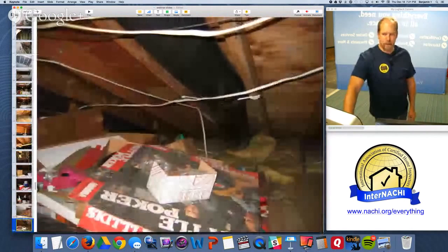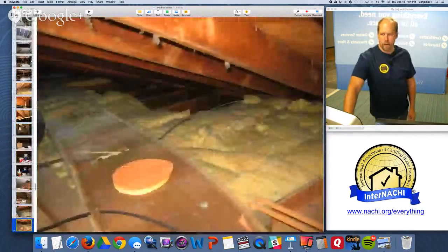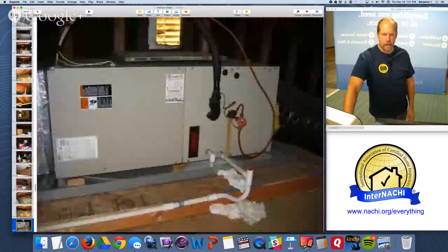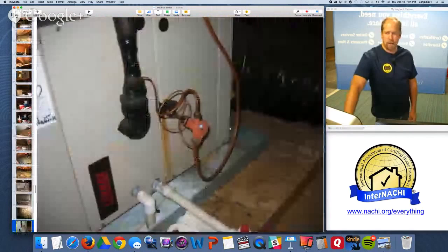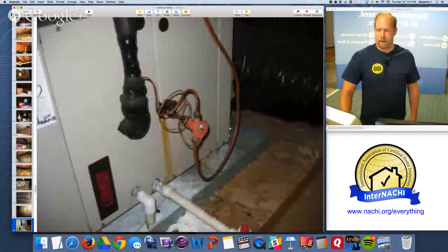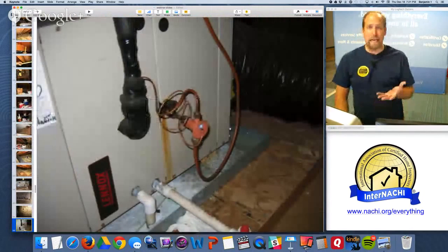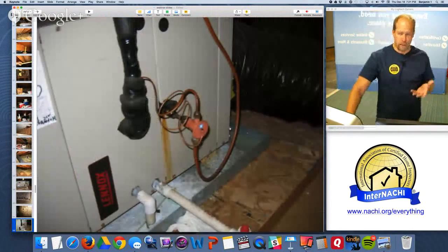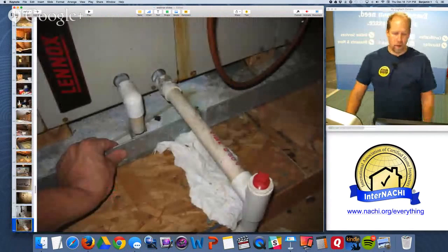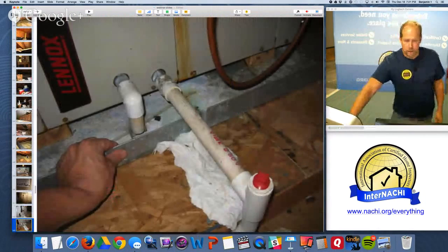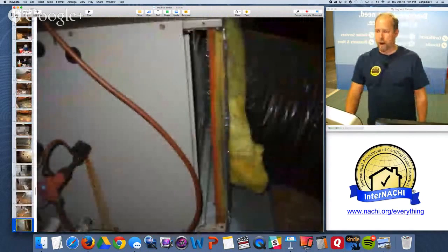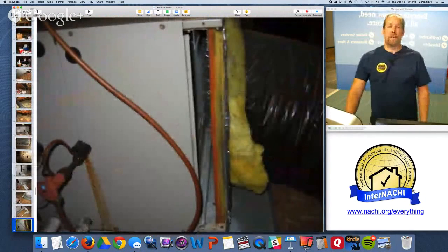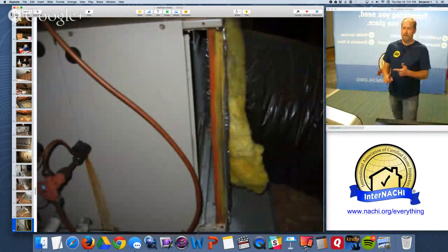There's the stairs going down. There's some duct work here and there. All looks okay. There's the air handler, service record, manufacturing label. There's a leak pan, water catch pan. That's great. A nice workable surface in front of the unit. It's all looking good. The drainage was installed properly, but the air filter is actually missing. The air filter is missing and the slot is open.